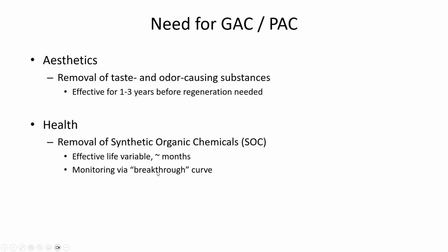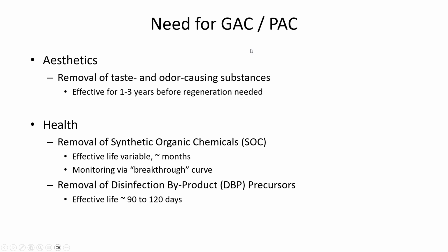So that's kind of when I installed a carbon block filter at my house, was during that Elk River spill, because that one, just coincidentally, had a flavor associated with it. They said that MCHM had a licorice flavor to it, and you could taste it in the water. But there may be synthetic organic chemicals that get into the water and aren't removed, and we're not able to taste them. And so I just figured maybe better to be safe than sorry and put a carbon filter on my drinking water. The activated carbon can also be effective at removing disinfection byproduct precursors.